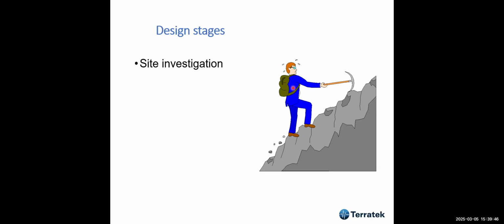I've seen this too many times. And usually most of the back analysis I have done in slopes that failed leads to an ru pore pressure value of 0.2, 0.3.